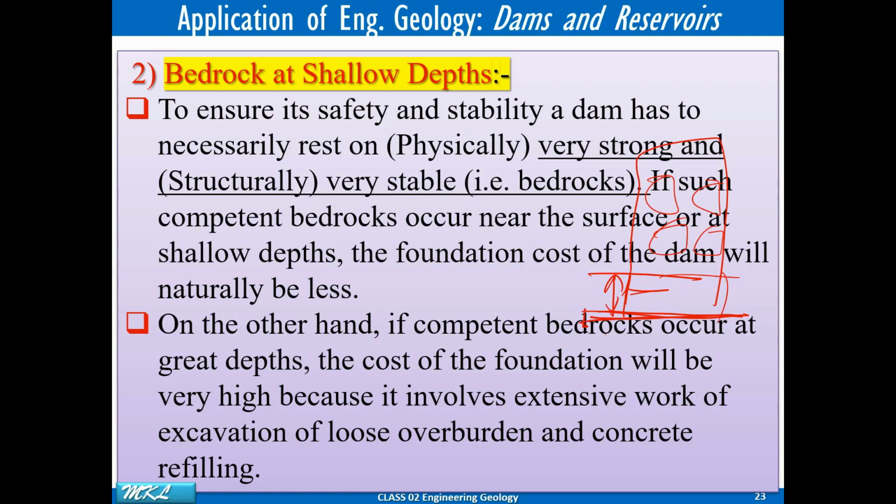Same thing happened with the dam also. If you found a shallow bedrock, that means it's a cost-effective technique. Now, this bedrock could be fractured, that thing you should avoid, or you have to take some remedial measures. Sometimes you find that it's heavily fractured, but you are having a shallow bedrock, so blindly you shouldn't go for the site. You shouldn't select that site for the dam.